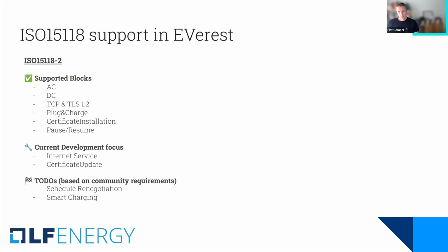On the ISO 15118 side, we have support in EVerest for ISO 15118-2. I've listed the supported blocks here: AC/DC, TCP and TLS 1.2, plug and charge, certificate installation, and the pause resume feature.